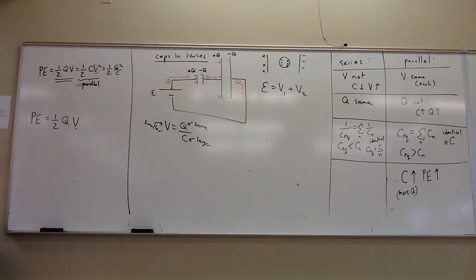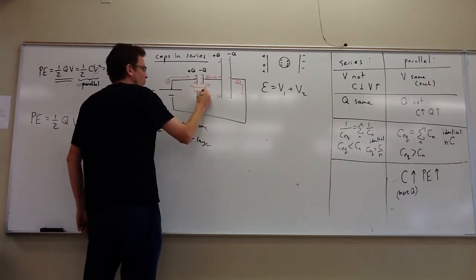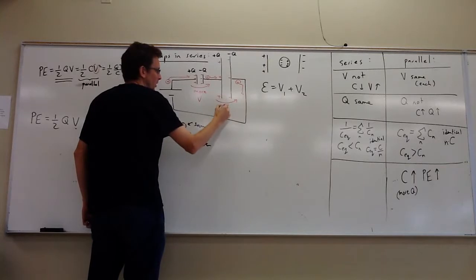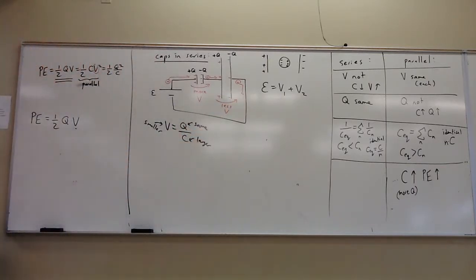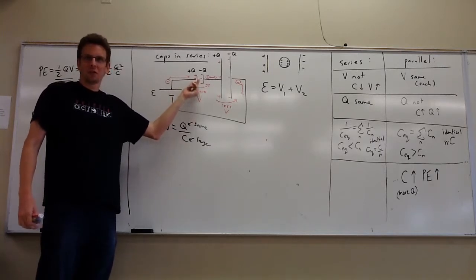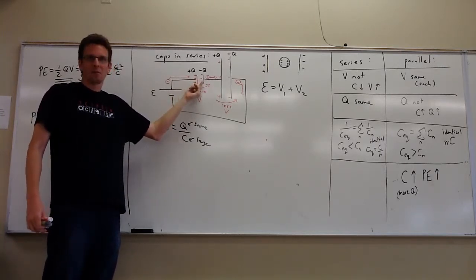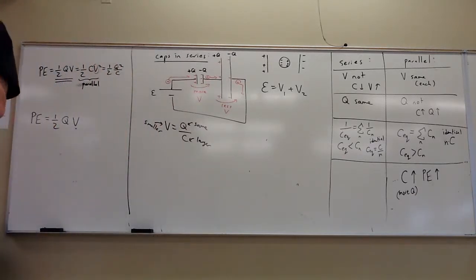That may seem counterintuitive, but let me try to explain why. This is a small capacitor that has a larger voltage drop, and this is the larger one, and it has less. Let's think about this. This is a small capacitor. It's not as good of a storage device, and you've crammed a bunch of charge into a very bad, small holding space. You put them in close together. That means you're going to have a larger voltage drop between one plate and the other.